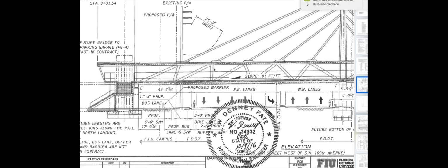They do have connections, concrete connections, but the concrete's weak in shear, weak in tension. So these would just be pretty much under tension at that point. Some of them under compression, but nevertheless weak in tension. So this was the one we understand to be in tension, compression and compression. And with that said,